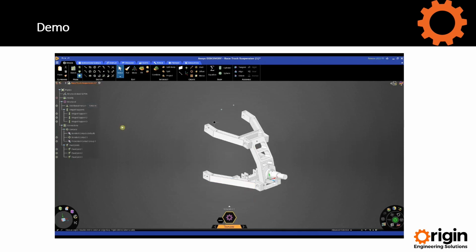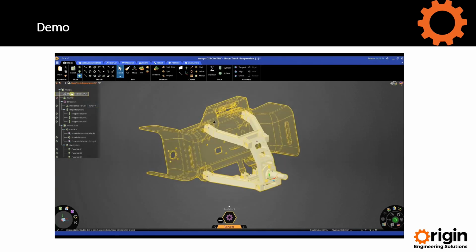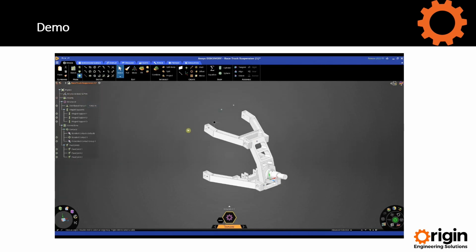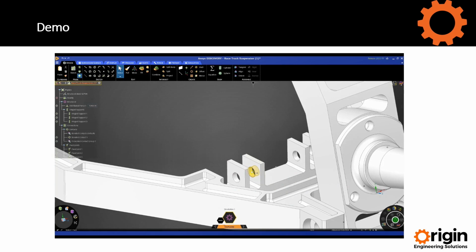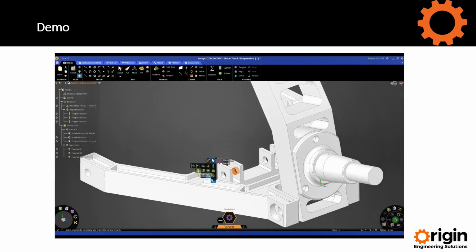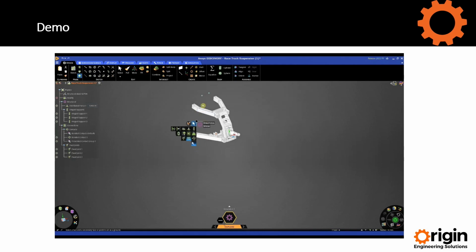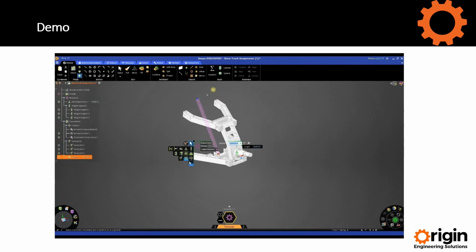So when we saw our parts, we can see that there actually are a couple of springs. So we can apply these using our spring tool. So we can again use this tool here. This is the new spring tool. Select a secondary location. In this instance, I've actually created a point in space, and we can select longitudinal or torsional. I'm going to apply a value of 1000. So that's applied it there.